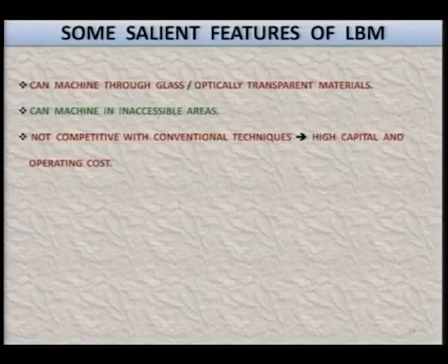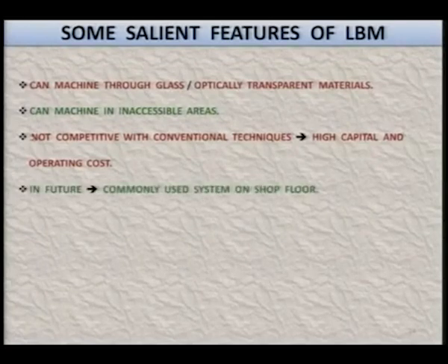Now, this is a very important point to take note of, that one should not try to replace laser beam machining under the circumstances where you can do your work with the help of traditional machining processes, because traditional machining processes are very economical, low investment cost and comparatively fast. Laser beam machining should be used only in those circumstances where other processes which are more economical cannot serve the purpose.